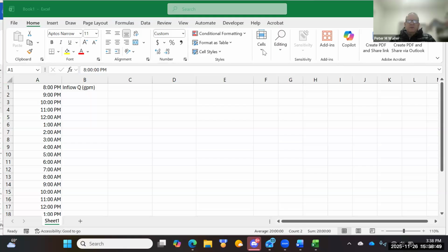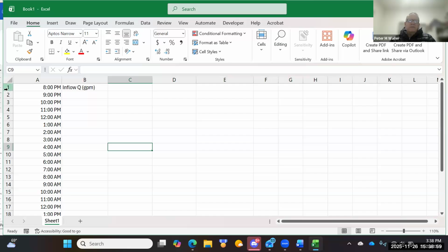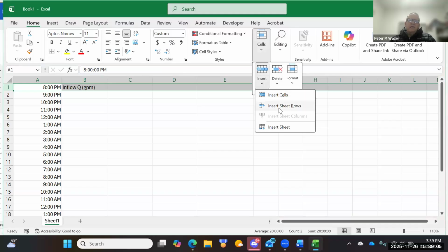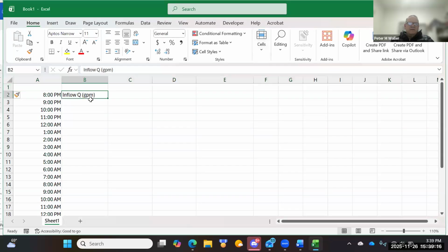So we don't have to run the well pump all the time, but we do need to run it longer than the sprinkler pump. So typically we'll set up a table with each hour. I'm sure we could figure this out analytically, but a lot of times it's just easier to figure things out in a spreadsheet, not to worry about any theory.